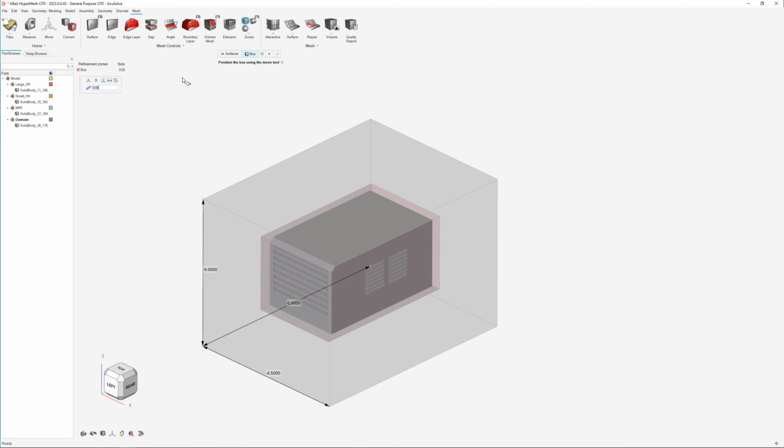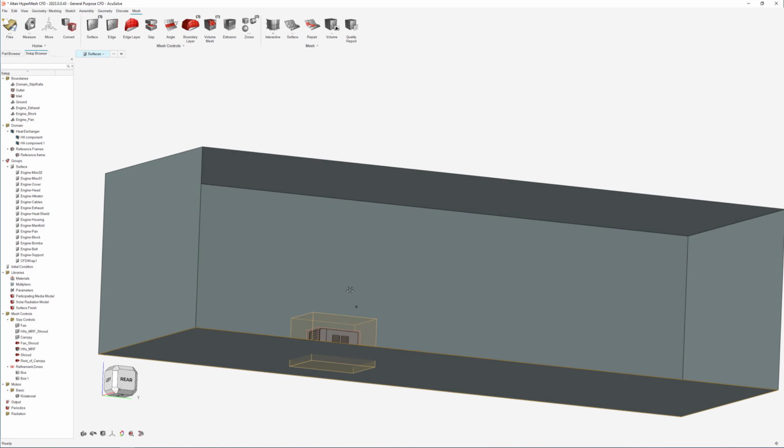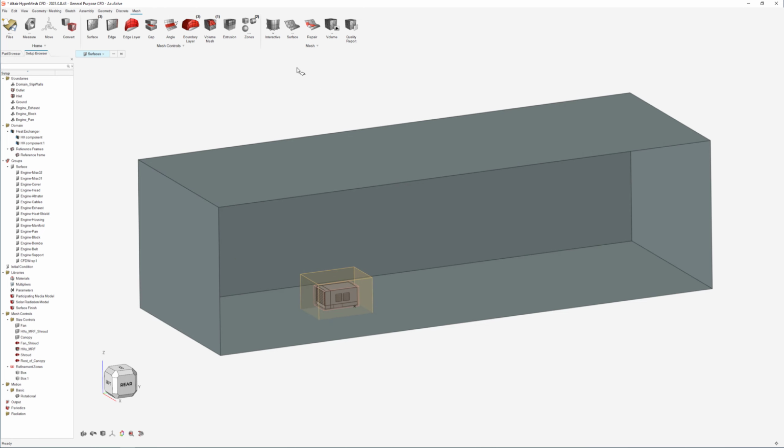As the second box intersects with the ground face, we should remesh it to ensure that this control is also applied to the surface and refines it accordingly. The average element size will be set to 0.4 meters as it was previously.